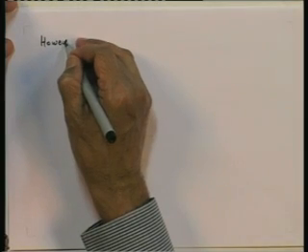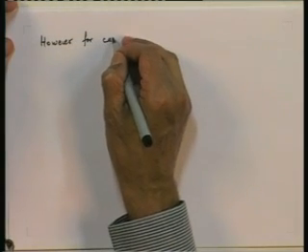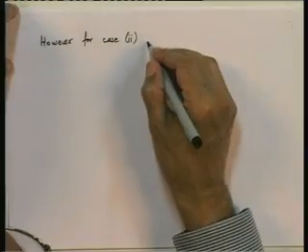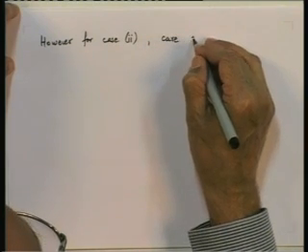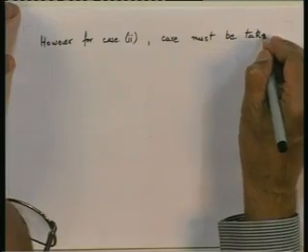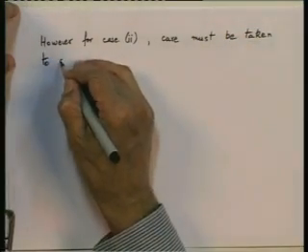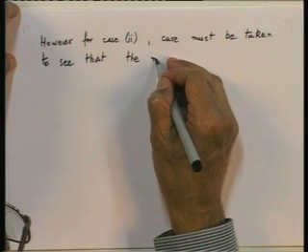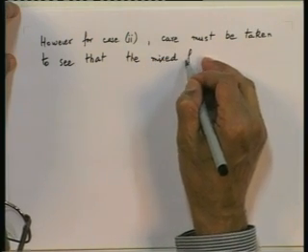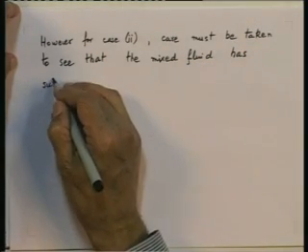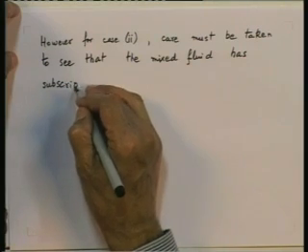For case 2, that is one fluid mixed and the other unmixed, care must be taken to see that the mixed fluid has subscript 1.